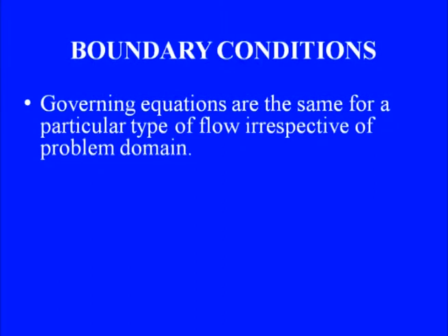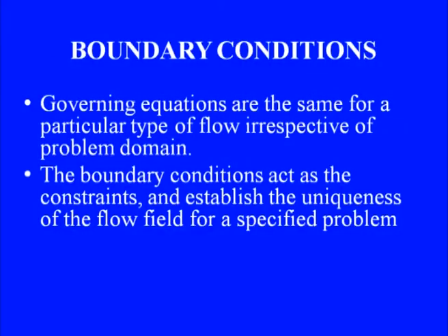And next we will have a brief look at our boundary conditions before we close this module. So, the governing equations which we had, continuity, momentum or energy equation, would be the same irrespective of our problem domain. Then what makes each problem unique? That uniqueness is imposed by what we call boundary conditions, which act as the constraints and establish the uniqueness of the flow field for a specified problem.